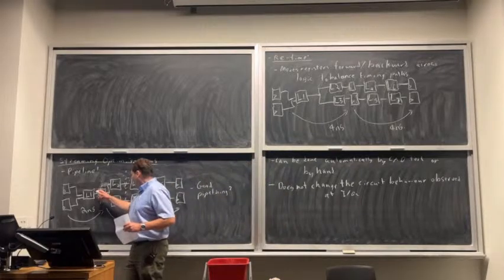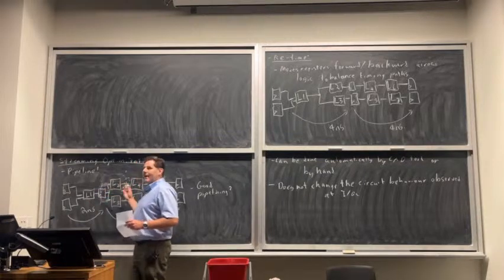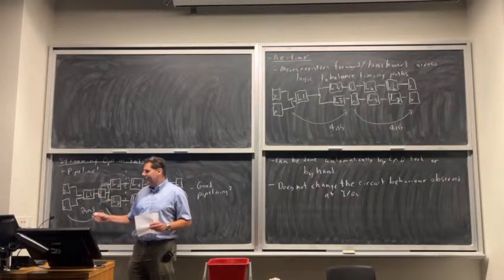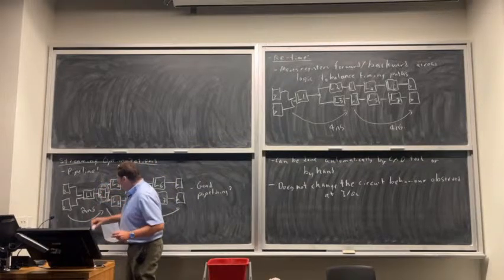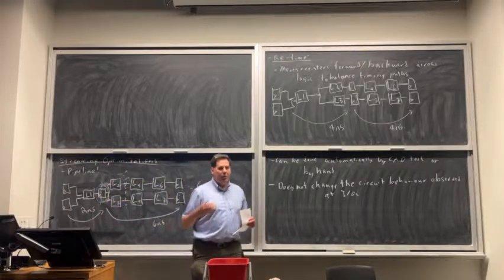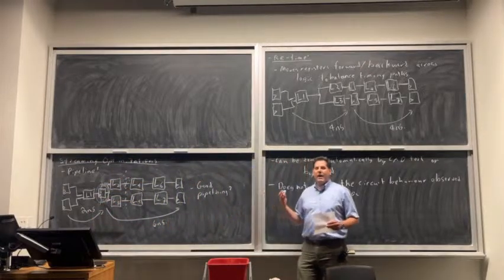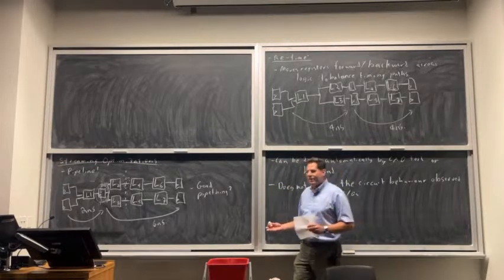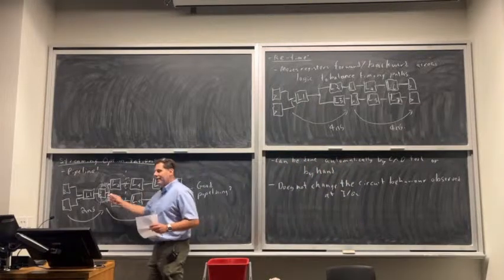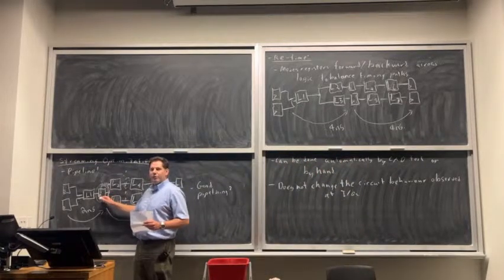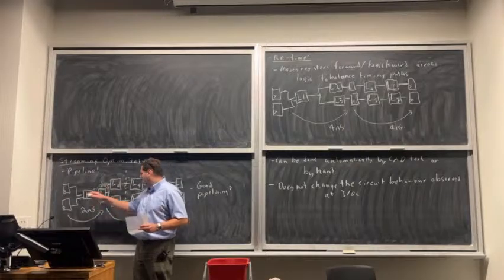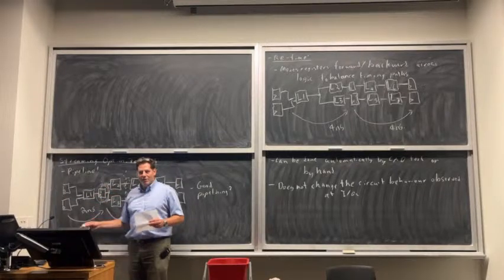What retiming does do is, if you look inside the circuit, these registers are different. This register in your HDL will have a name. It has a function that you understand. You know what this thing is doing. Maybe this is a counter, for example, or maybe it's an enable signal under some condition. But you actually know what this should be.